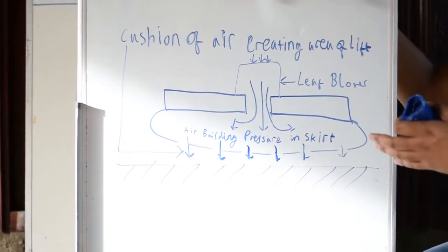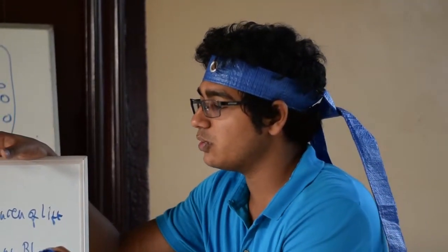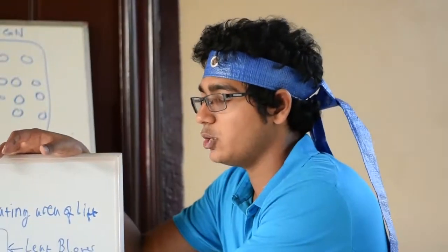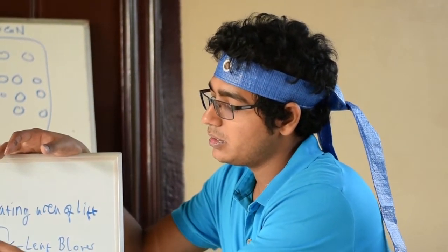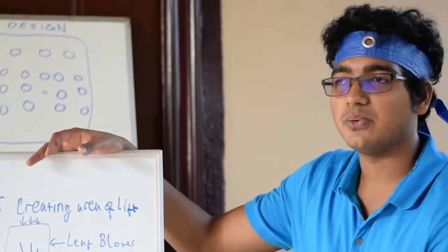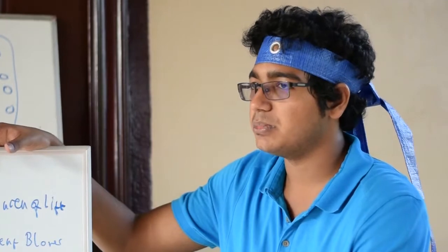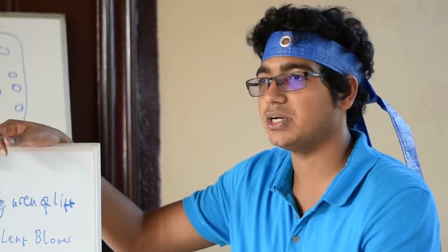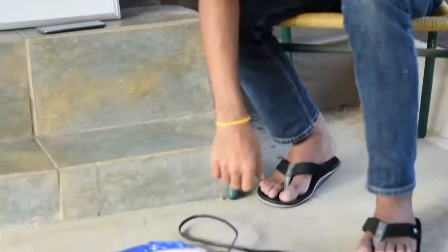To try to alleviate this, we initially tried to create more holes in the side where there was more air pressure, well, more air volume, which was the side opposite to the pilot. But this didn't work so well. There was still too much friction between the skirt of the hovercraft and the ground, and too much force was required to push the hovercraft. At this point, we decided to build a prototype before rebuilding our current design in order to know the way forward and to make sure our design was working. Therefore, you can see our prototype beneath.